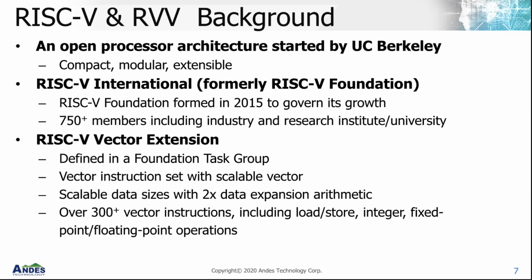The operands are in fixed locations, no status bit, no predication, no load or store multiple. So the instruction set is pretty simple to design. The RISC-V ISA sets aside some of the opcode space for custom instructions as well as for standard extensions. One of the most exciting extensions is the vector extension, because it opens the door to many AI and ML applications.